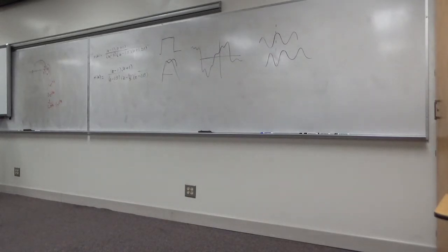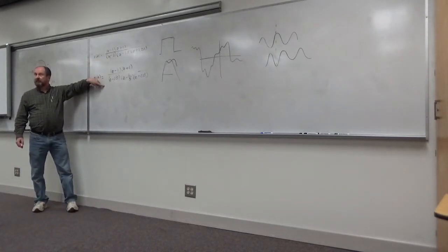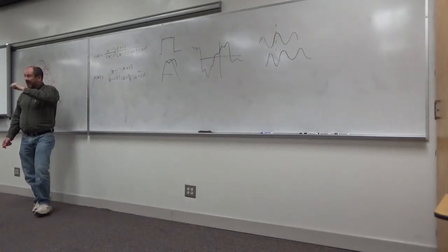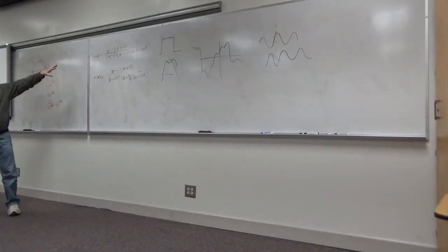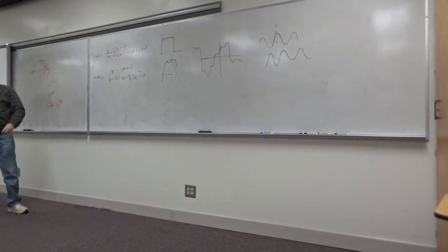So, if you were to encounter a system with a pole outside the unit circle, and you don't want to mess with the gain response. So I keep saying that, gain response, gain response. What do you suppose happens when you flip them inside? These two are different functions, do we all agree on that? We just proved a few minutes ago that the gain response for those, take the H of e^(j omega) and take the magnitude, is the same.